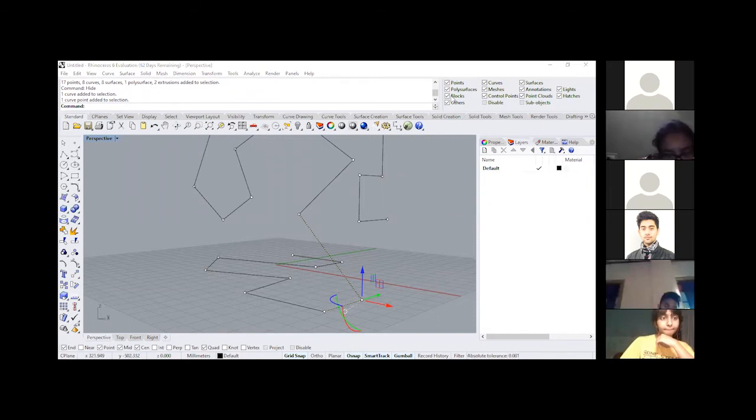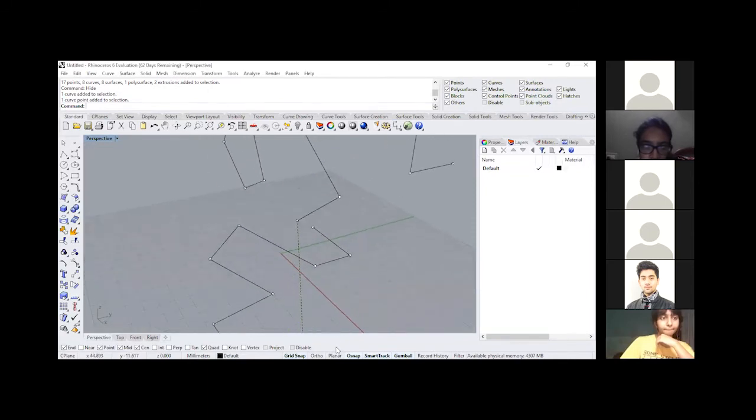Okay, Disha, I think I missed your chat over here. You were asking me to repeat some part. Which part? I just wanted to know why the part about the z-axis, you said the z-axis is missing. Yeah, so that is because of the construction plane, which we are discussing now. Okay. Perspective has a construction plane set to world XY plane. As a result, it won't snap to the Z-axis. Okay. Got it? Yeah. So now we're just learning a little bit about the planar section over here.